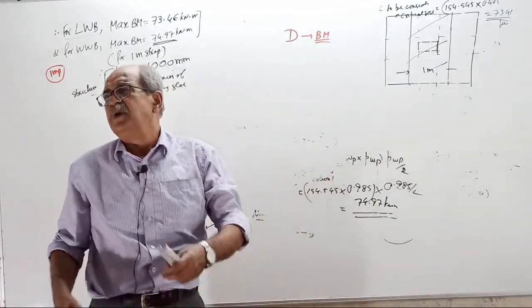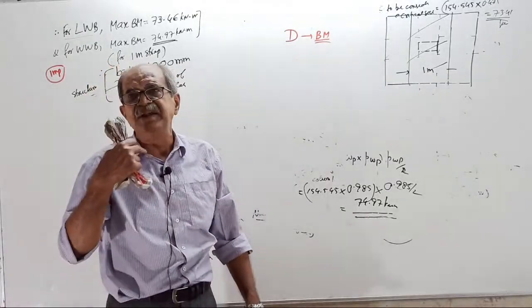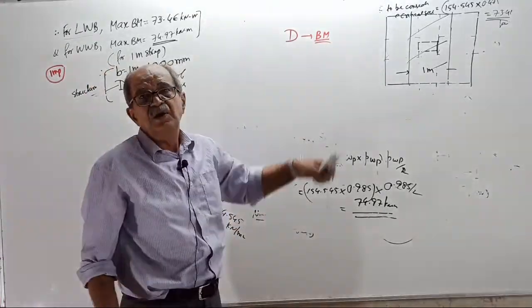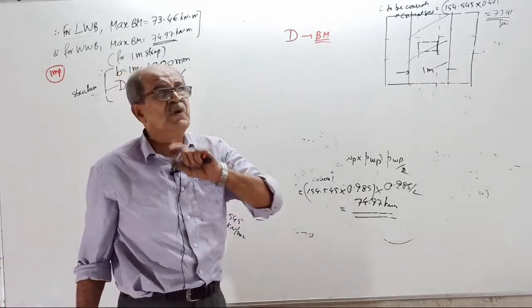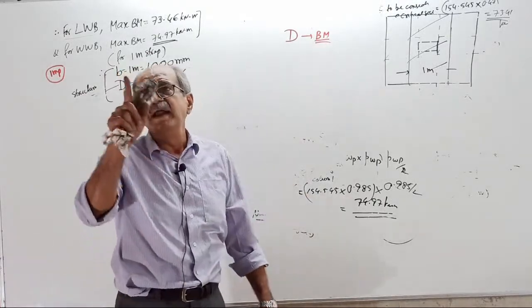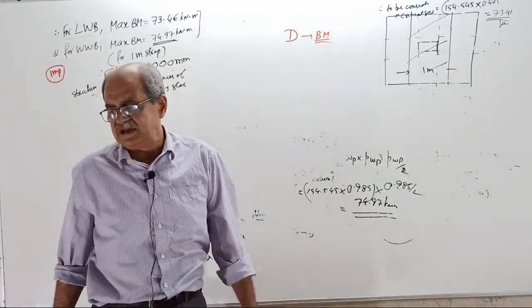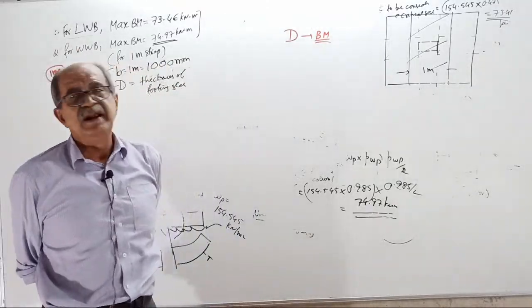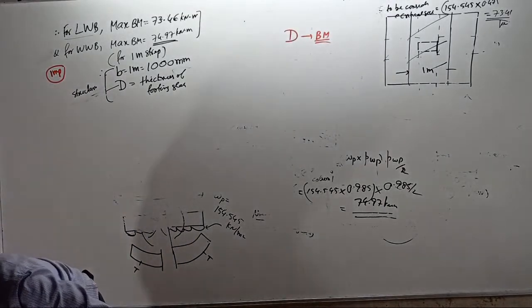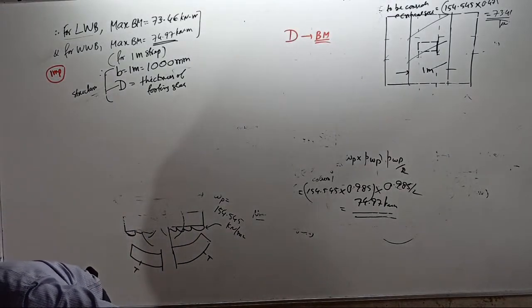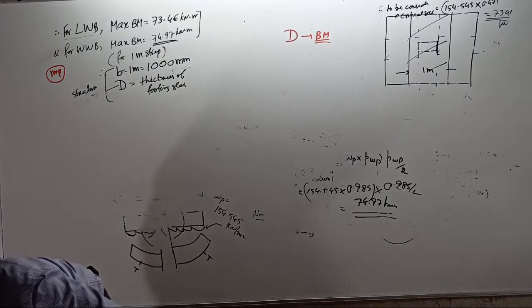It will be 100% unsafe in shear, my guarantee. Therefore, you first find the thickness of slab depth based on bending moment, then provide a higher value or a lesser value? Critically, shear.